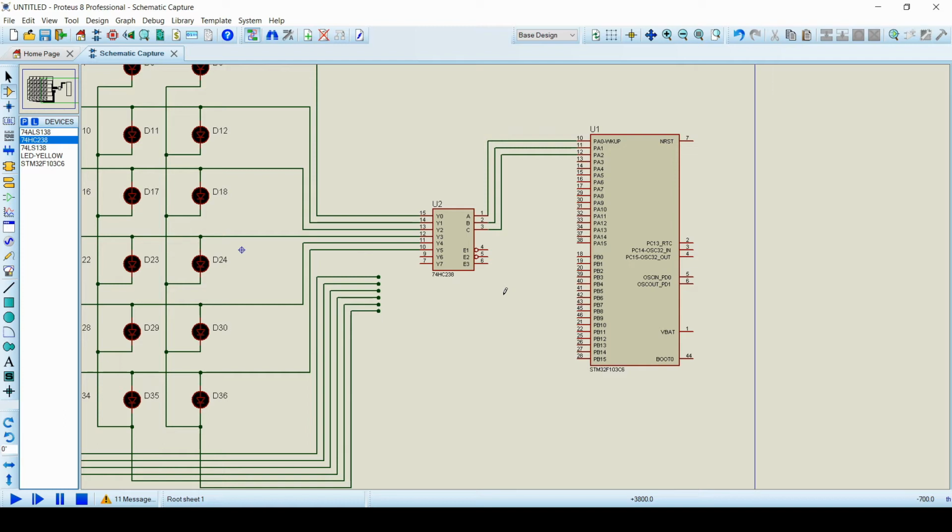As you can notice, E1 and E2 are active low inputs. So we will connect those two signals to the ground. And connect E3 to the power. The reason for selecting the non-inverting demultiplexer will be given in a minute.